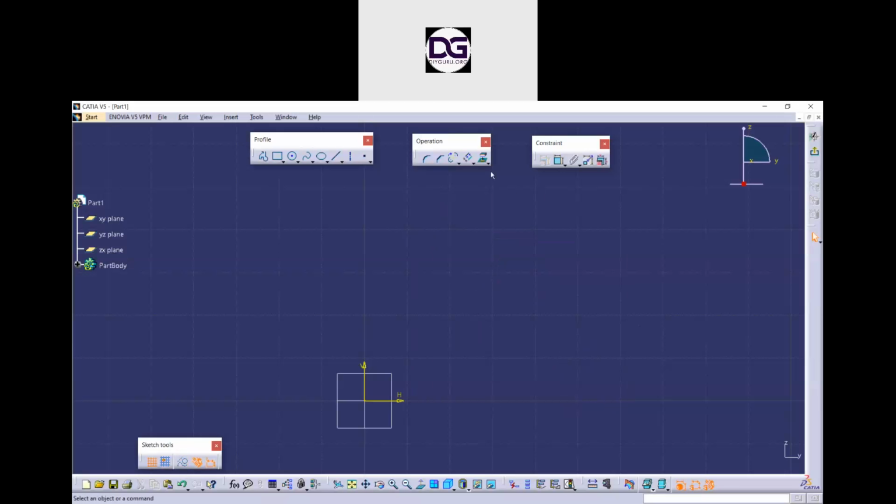The next is the 3D geometry projections tab. This is usually used when we already have a 3D object and we want to take that object's reference for our next 2D sketch. Like we want the corner intersections or the edges of the 3D object into a 2D sketch.